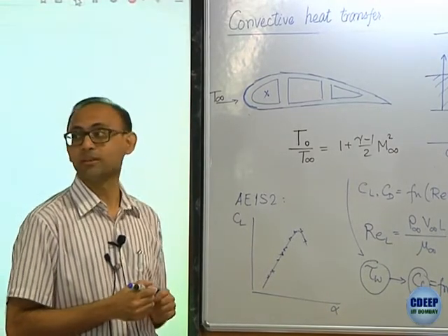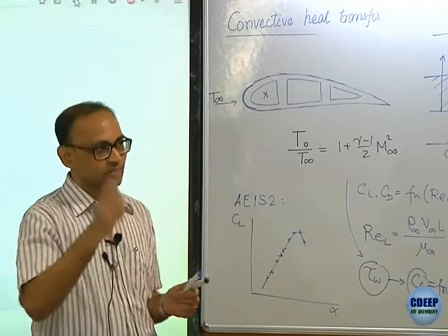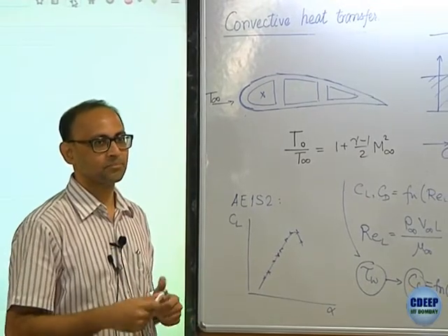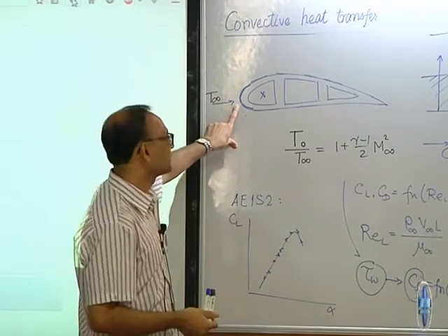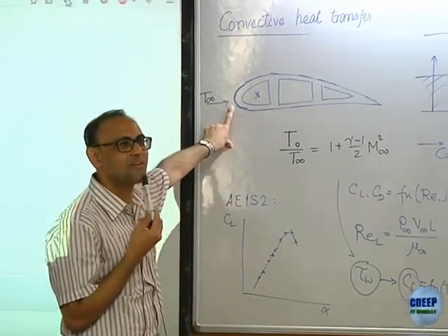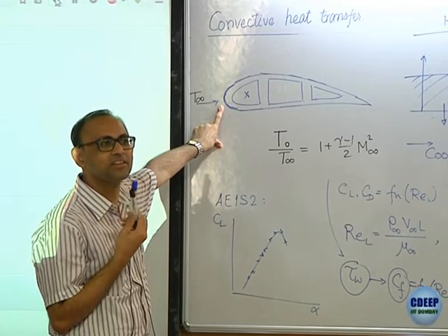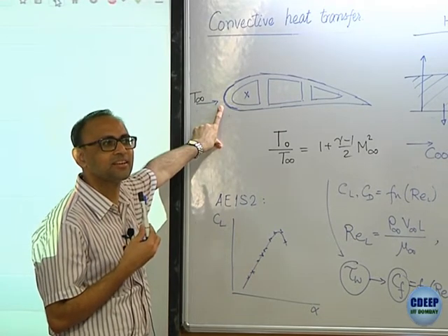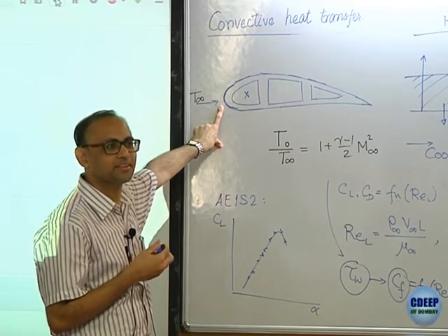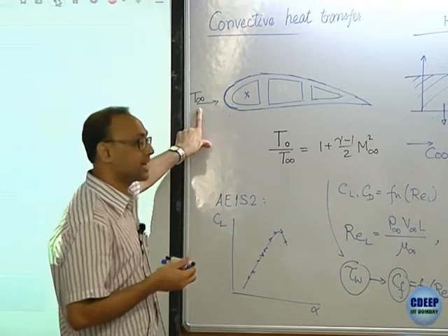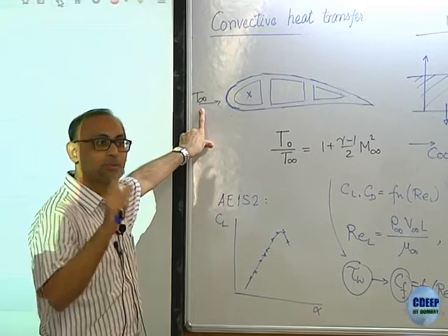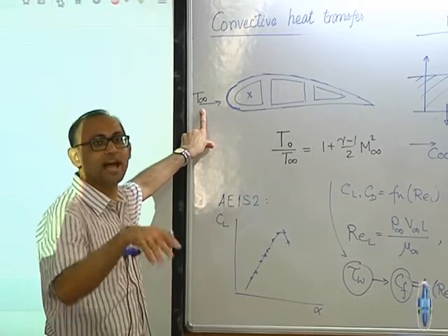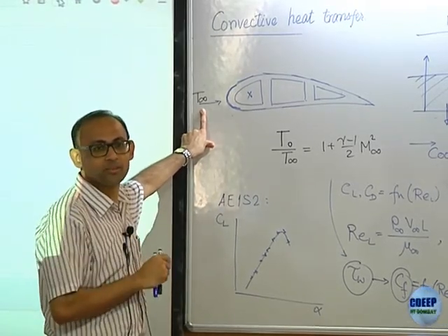And now tell me, if the blade was not stationary but spinning, would that increase or decrease the stagnation temperature? Increase. It's a relative Mach number. The static temperature of a fluid does not depend on whether the fluid is moving or at rest, but total temperature does depend on that, because the kinetic energy gets added to it. It's a frame dependent quantity.